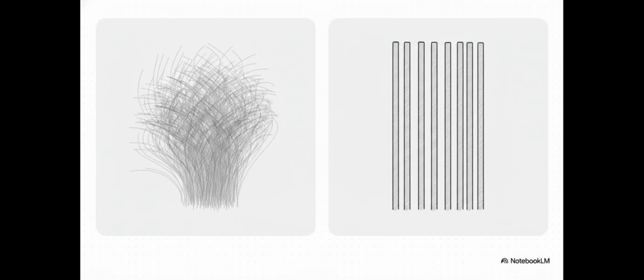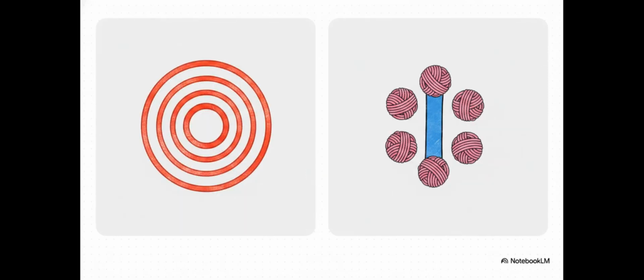It uses slightly thicker, optimized strand counts, around 30 to 34 AWG. And this is precisely calculated, because if the strands are too fine, they'll actually birdcage, which is basically a disastrous bad hair day where the wires bunch up and snap under rapid automated acceleration. And this brilliantly illustrates the core architectural difference.